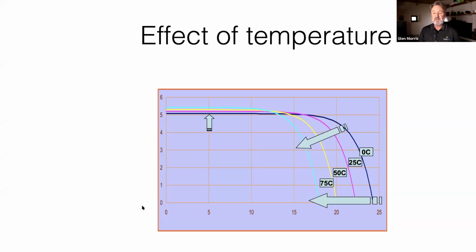Sam says, some panels come with cooling systems in hotter areas? Generally no. Like I said before, it's probably not worth it. With all the fashion for black modules, has this had an effect in terms of their operating temperature? Just because it's black doesn't actually mean it's hotter. It can actually mean it's got a greater emissivity characteristic, so it may actually reject heat more effectively. I think that's a manufacturer's question. What is the effect on temperature on their particular module?